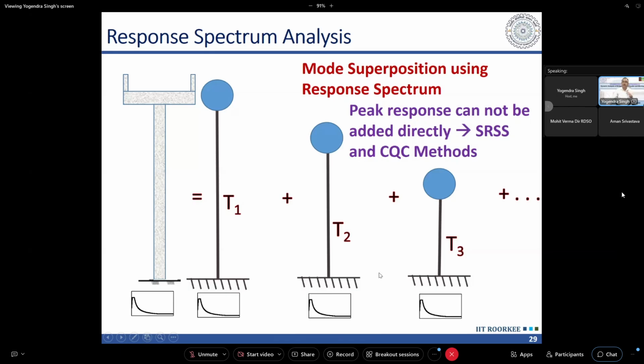Superstructure will vibrate, but the substructure will not vibrate. And as a result, the substructure will remain more or less static, or rather it will be moving rigidly with the ground. That is more appropriate to say. So you will not get any mass participation from the substructure.